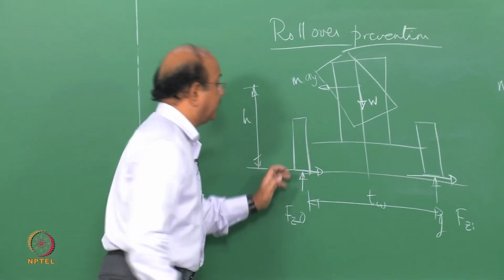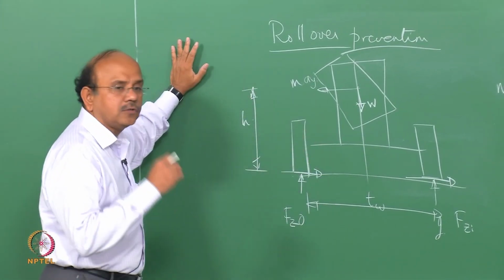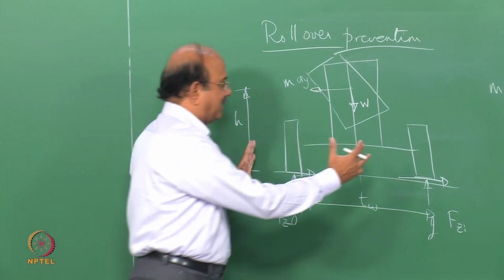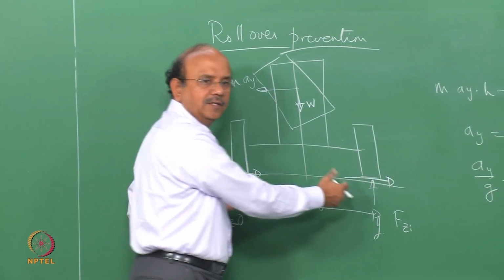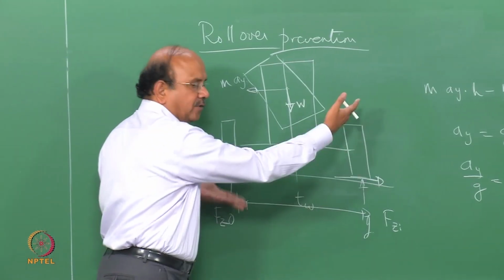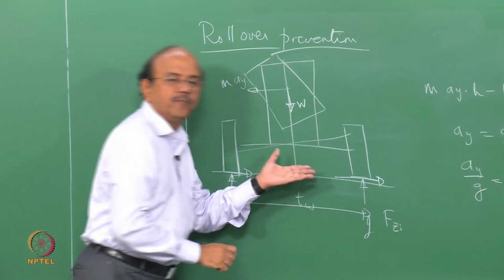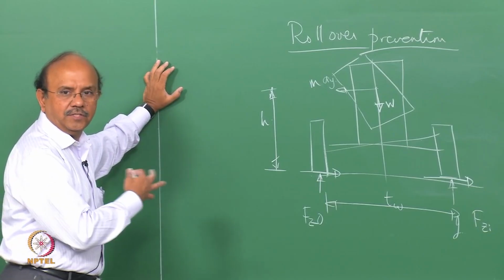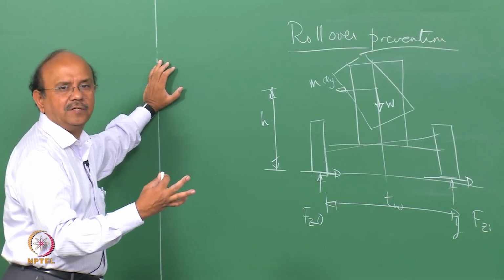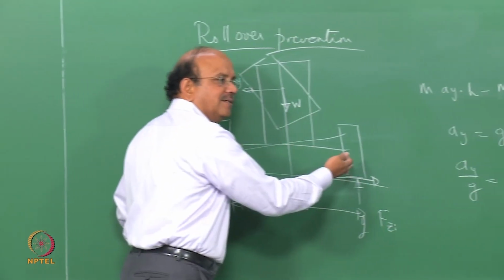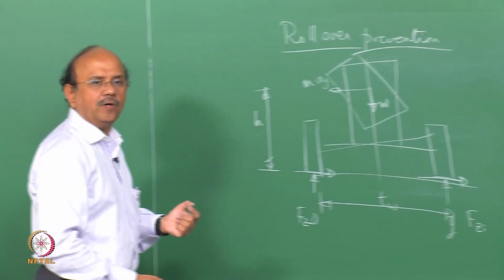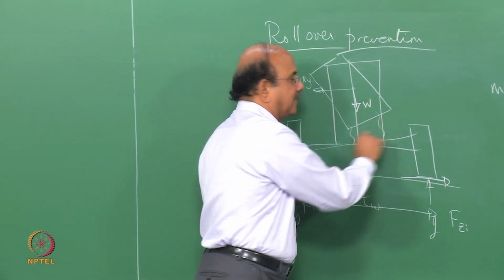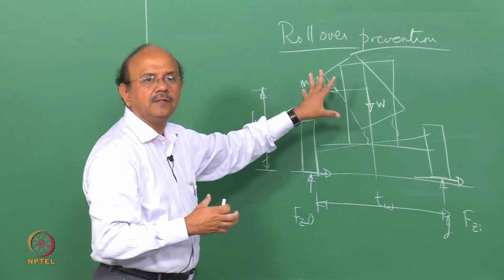So the roll is also affected. There are two rolls here. One is the roll of the unsprung mass, which is basically due to the tire stiffness. Let's look at the suspension system or this axle system, which is a rigid axle system, which is there in most of the commercial vehicles. And the second one is that on top of it is going to sit this sprung mass, and that sprung mass is now affected by the roll stiffness.